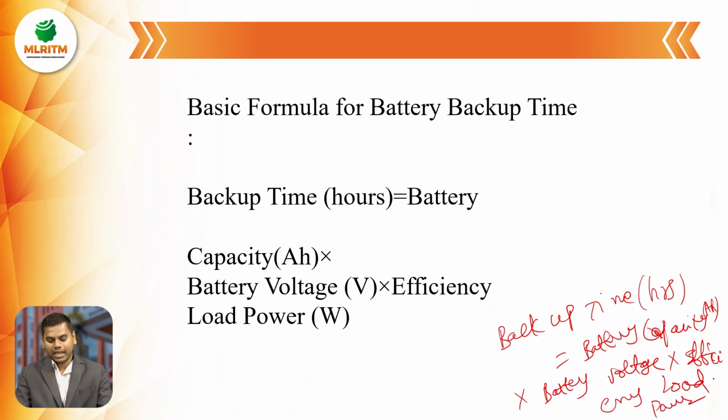So this is the basic formula of the battery backup time. Backup time is equal to battery capacity into battery voltage into efficiency divided by load power. So these are the battery backup formula.